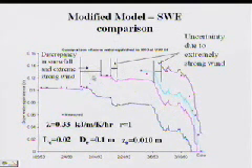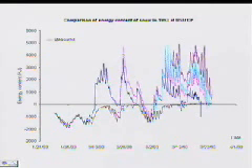But we were able to identify that all the times when it occurred were times when we were unsure about our data, where there was an extremely strong wind and we weren't able to record well the snowfall because we had an unshielded rain gauge. And so we weren't sure what's going on. So we would then reinitialize the model after each of these occurrences, and it would tend to model the meltout following that. And these are some of the parameters that had to be adjusted to get the model to work with the revised conditions.